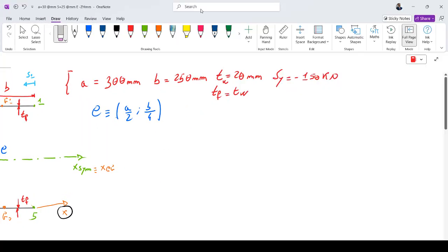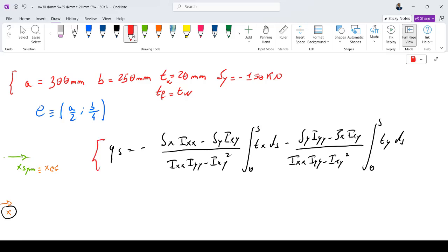Clearly, in this case, we have the general relation of a generic shear flow. So we have this quantity here divided by the moment of inertia, the product of inertia, and the shear load along x and y direction. Now, if we have a one-time symmetrical section, clearly the product of inertia Ixy, and you can prove this, is equal to 0 millimeters to the 4th power. Also Sx is equal to 0 kilonewton, because we have only Sy.